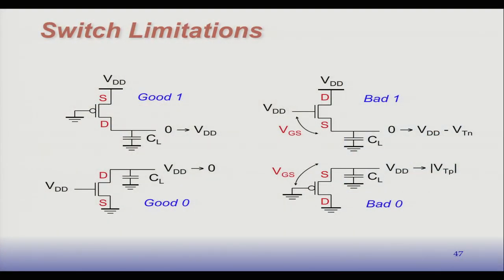If we try, as shown here, to use an N-type transistor to pull up, in this case there's a capacitor here, and we're charging up the capacitor. That's pulling up the voltage. We'll get to a point where the voltage on the capacitor gets to VDD minus VT, within one threshold of the transistor turning on, and it essentially turns itself off.